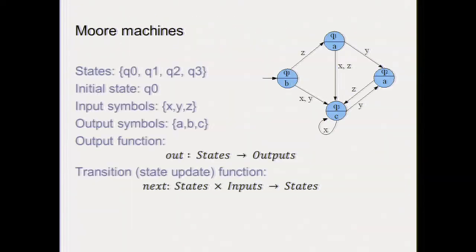Okay. So Moore versus Mealy machine. Moore machines are such that the output depends only on the state. And so in the representation of a Moore machine, you don't have to label a transition with the output; you can label the states with the output, because the output depends only on the state. This also tells you that when you land in the state, the output is computed. Which means that when you compute the transition, you have to take the previous reaction index, which makes life easy. Okay, so that's the thing.